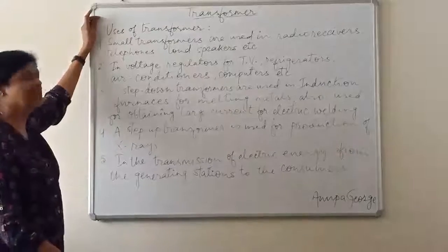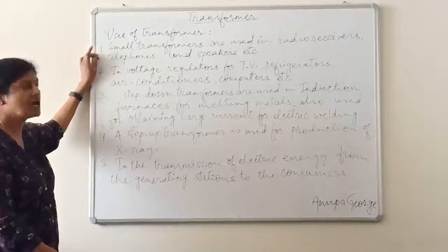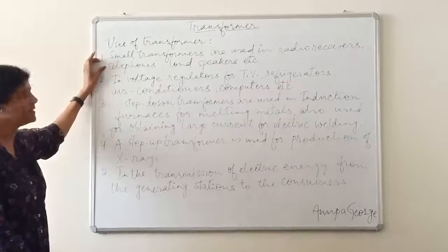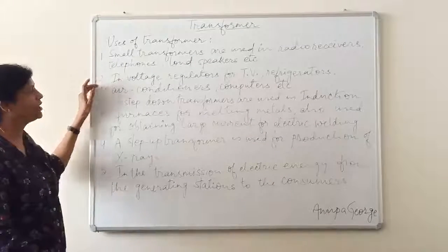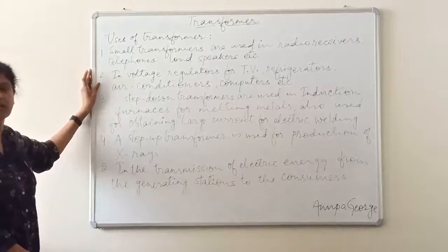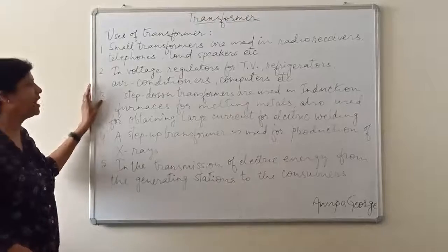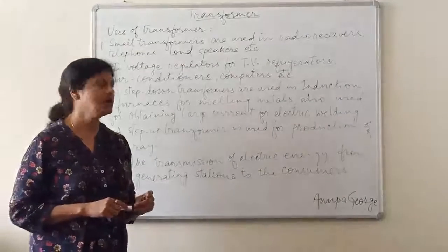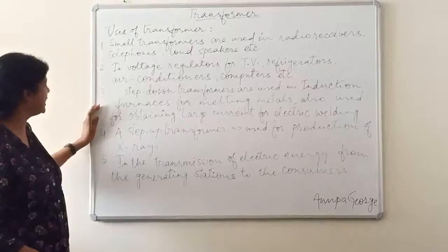Some important applications of transformers are, number one, small transformers are used in radio receivers, telephones, loudspeakers, etc. Second, the voltage regulators for television, refrigerators, air conditioners, computers, etc. Third, step-down transformers are used in induction furnaces for melting metals, also used for obtaining large current for electric welding.